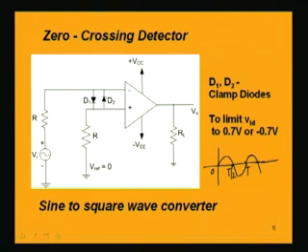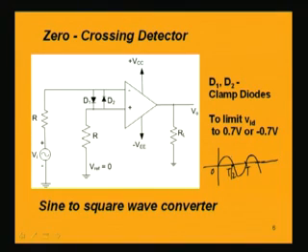Now if we consider a sinusoidal input voltage Vi, we have an instantaneously varying sinusoidal voltage at any point, which we compare with the reference voltage 0. So, we are now comparing it with 0 voltage. As 0 is the reference, we only have two portions to consider, that is the direction only, whether Vi is positive or Vi is negative. In the positive half cycle, Vi is greater than 0.